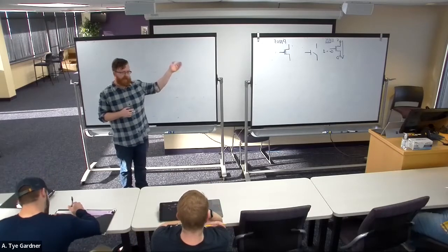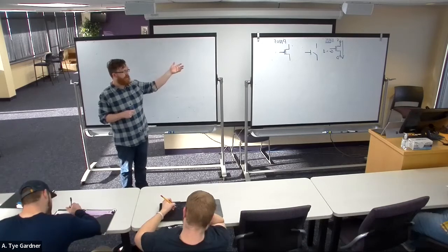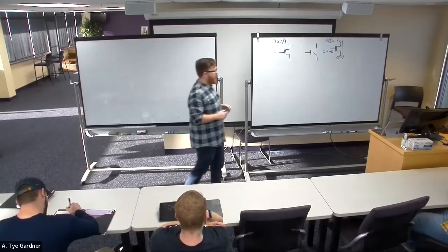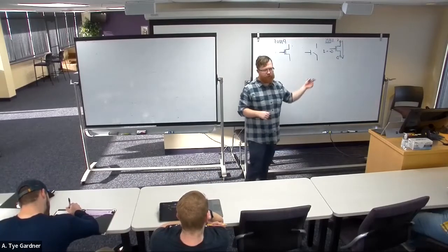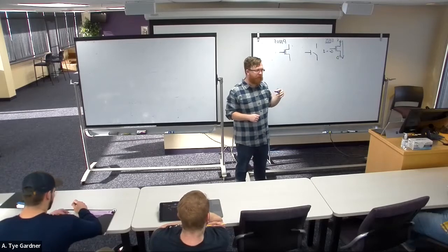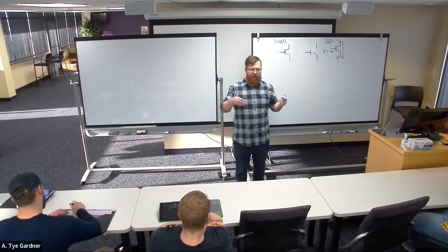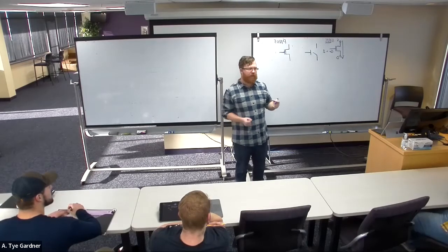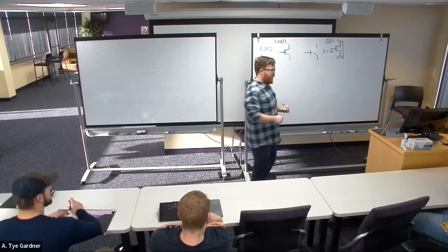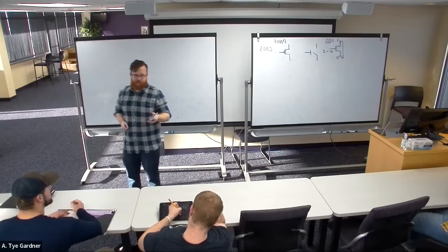These two devices function as the beating heart of all things electronic, all things high-speed electronic, digital especially, right? There are other types of transistors. We don't need to know them yet. You will learn them later. These are two, and when we take an NMOS and a PMOS and we stick them together in an intelligent way, we get CMOS. The C being complementary, meaning they work together, okay?